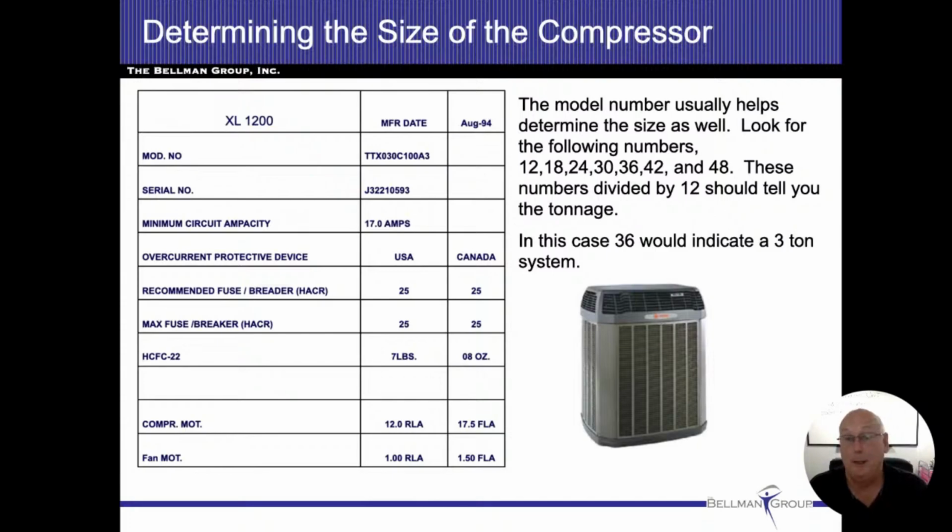That's not a problem. And if they want to go with a 10 gauge wire, they could do that too. It's a little more expensive, but it's safer. But by all means, when the manufacturer of the air conditioner said this is the minimum, this is the cheapest you could go and still make it safe, then it's still considered safe in their eyes. All right, so off of this data plate, we know our maximum breaker. We know the wire size that it should be. We know how big our system is, and we're able to determine how old our system is too.